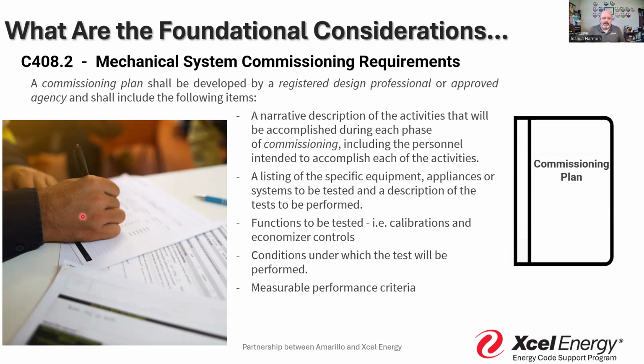Now, this is where we get a lot of plan reviews for residential. And I've told you this before, it still drives me up a wall. We get everything designed except for mechanical, and the mechanical comes in as the deferred submittal, and I literally have 3 that I'm supposed to work on today where the house has already started. Now you get your Manual J, S, and D. I need to see the duct design, equipment design, equipment selection, so I can evaluate: is this going to be the right system?